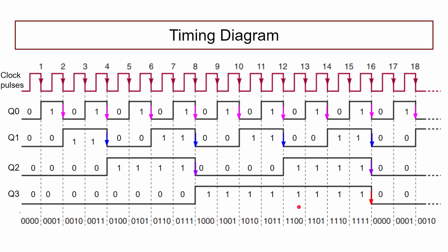In order to achieve this, all we require is T flip-flops for generation of Q0, Q1, Q2 and Q3 with T value equal to 1. For producing Q0, we supply the clock pulse from the external clock source, and for generating Q1, we take a T flip-flop to which the clock is supplied from Q0.